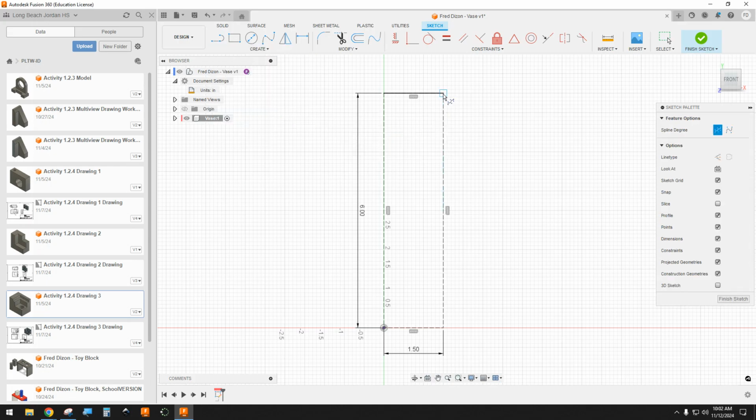You're going to click on the edge of that line, and then just click somewhere here, not a specific distance, but you'll notice as you curve the spline, it curves the line for you. You can adjust them to a specific point, but when you are creating splines, you want to make multiple points. At this point we want to go straight here. So I want to end this spline, so I'm just going to double click.